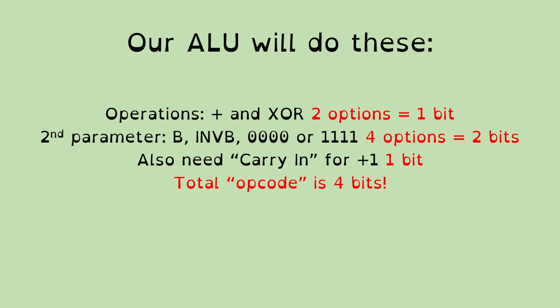So actually what we're going to do is we're going to cherry pick the 6 that do the things that we actually are looking for, and save the other 10 opcodes to do other things, because we only still have 4 bits, and although we want our ALU to be as versatile as possible, we've also got to be able to give instructions to the CPU to do things like move memory around and do jumps to get our conditional things going on.